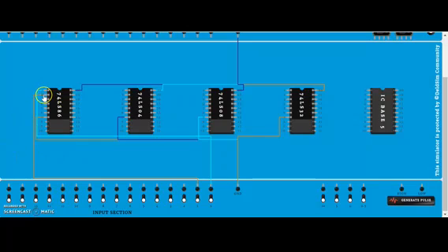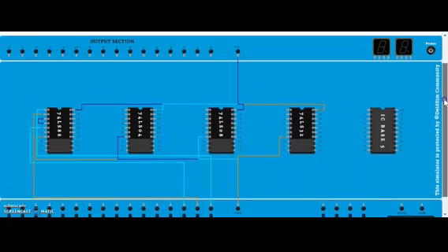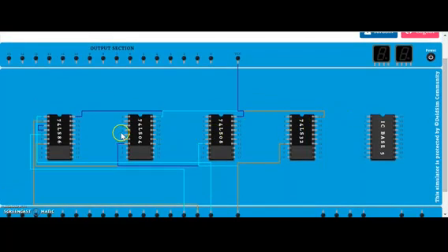The output of this 1 and 2, whatever output it will be generated, is going to be inside this pin number 4. And the next, B in, this fifth pin is our B in, from 5 to this 2. And the output of our XOR gate, A XOR B XOR B in, that is 6. This 6 we will connect to output, which gives us the difference.